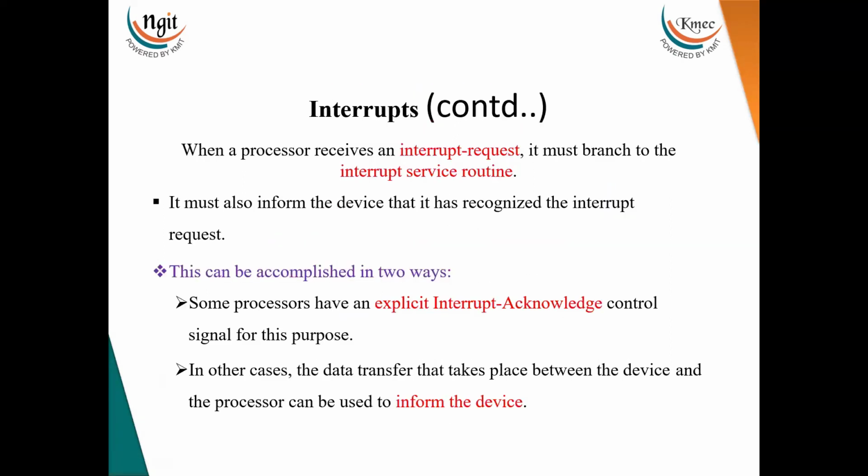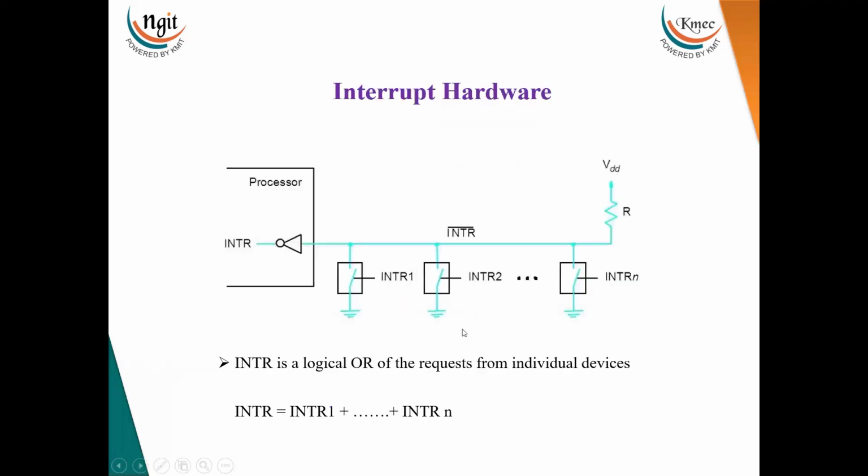Now, if more IO devices are sending the request signal to the processor, then which device's ISR is being executed is supposed to be known by the device. So for that, after receiving the interrupt signal, the processor will send the acknowledgement signal to the particular device. Means what? Whichever device's ISR is being executed, for that device it will send the acknowledgement signal.